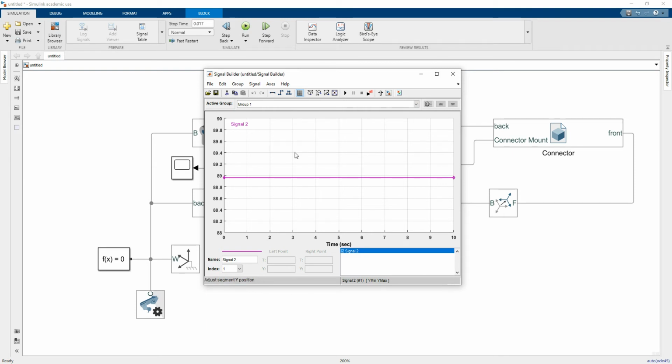We can choose all different directions, and it's great for what we need it to do. So what I'm going to do is try and restrict my T value. If I go to change time range, see how it goes to 10. What I'm going to do is set that to 0.017. Click OK. And now look at that. That is the overall time period.